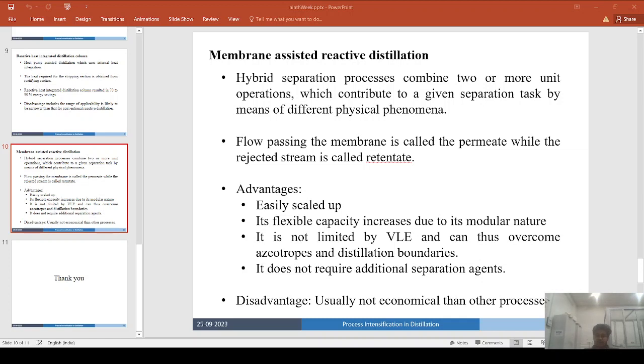Dielectric heating is mainly affected by two mechanisms: dipolar polarization and ionic conduction. In dipolar polarization, the heating is induced by molecular friction due to the rotational motion of polar molecules induced by the electric component of the microwave field. And in ionic conduction, the ionic bonding of many refractory compounds such as carbides and nitrides allows for ionic diffusion under the influence of an electric field.